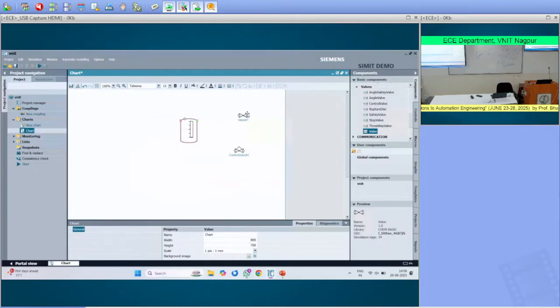So it will be just manual valves, or signal valves like 4 to 20 milliamps that you have to generate, and the valves will be there. You can give that data. If you want to change a valve into a pneumatic valve, that is not possible in this. These are manual valves. If you want to change it into signal-based valves, that is also possible in this. Here we have signals coming from controllers, which is also possible.